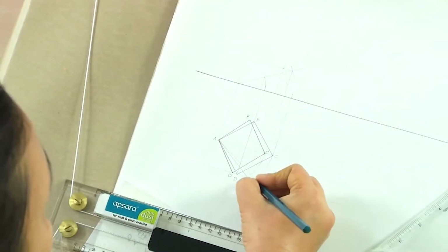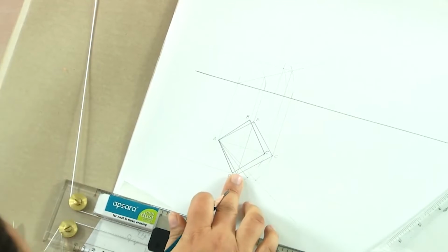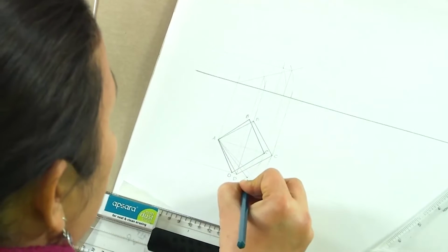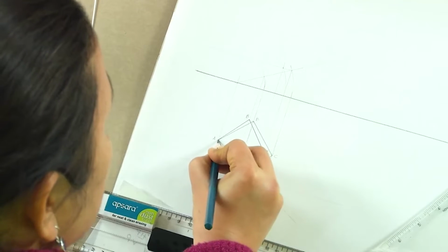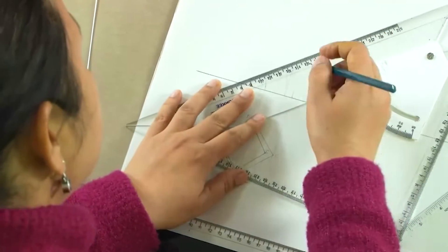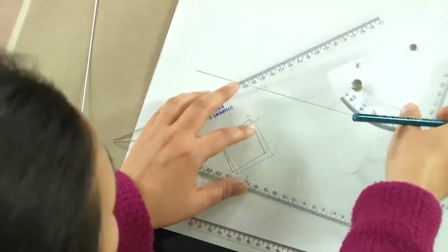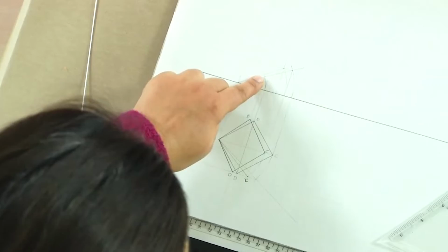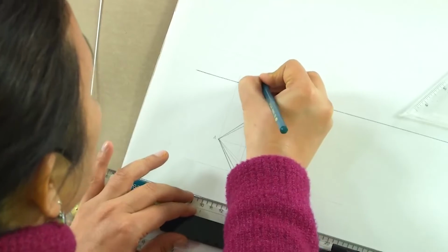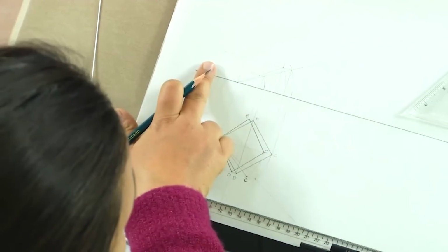So, now what we have drawn so far is this final C, which is inclined at 30 degree to both the horizontal plane as well as the vertical plane. So, this is the final C. So, the A point remains the same and C is here. So, we have this AC, and exactly the same thing we can do for this point B. So, we will get this point B, which will be here. So, we have the points B and D, which is represented by this horizontal line.